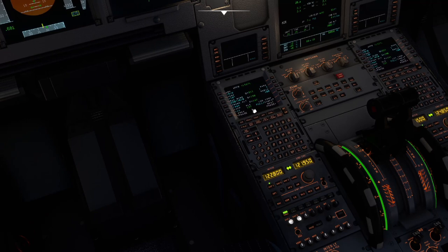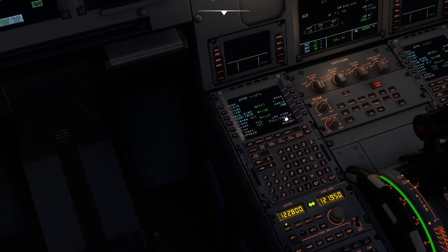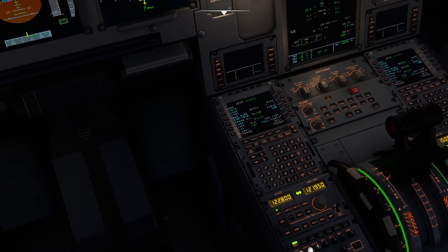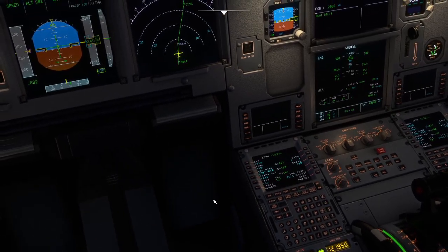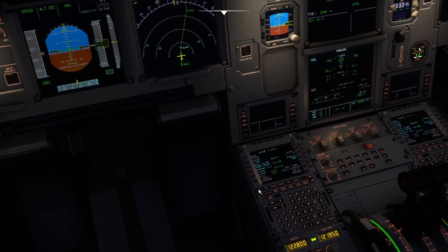Good enough. The A320 fly-by-wire is pretty good, so it knows what weight you're going to be at Heathrow. So it's like, okay, if you want to go full flap, your VREF is basically 127 knots, or what I would call VREF. Apologies, Airbus pilots. And then, of course, most of us will be adding on. Most companies will have you add at least 5 knots, which is where this VAPP 132 comes in. So that's the basic ref. Here's your app. So 132. 10 knot winds, pretty happy. 132 is going to work for us today.